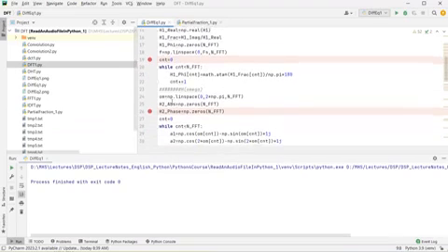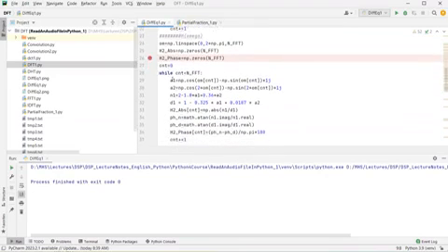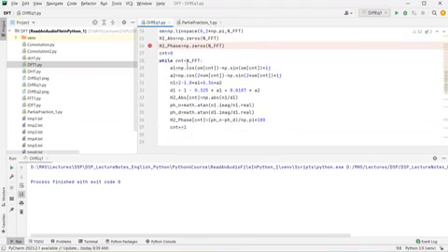And now here we compute the results directly for the frequency response. So we define omega, linear space from 0 up to 2 pi, taking NFFT samples, and providing the absolute value of H2 and phase. Using a while loop, you see, we have written Python code from scratch.